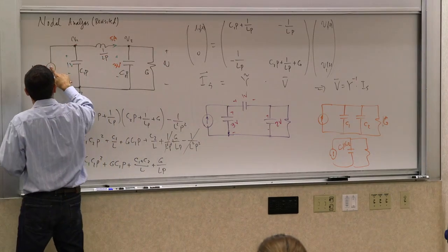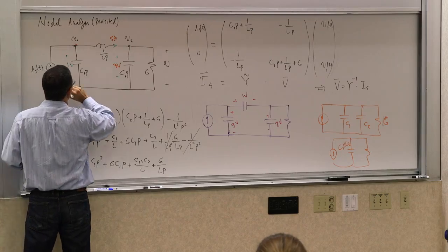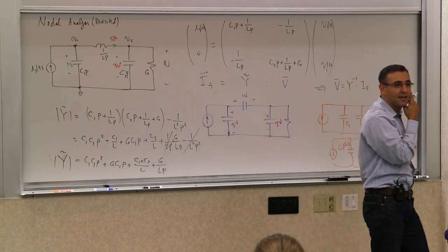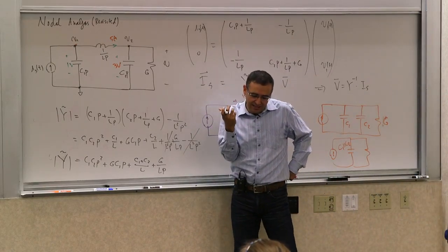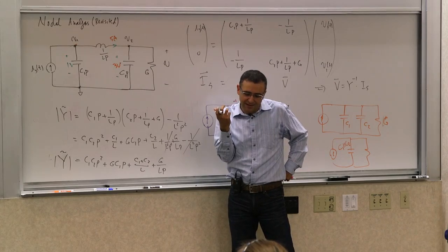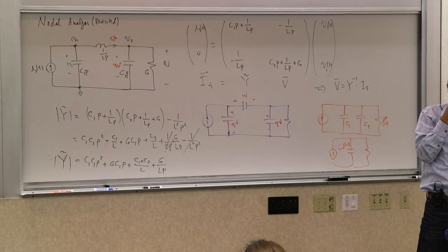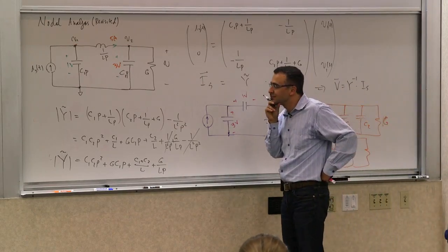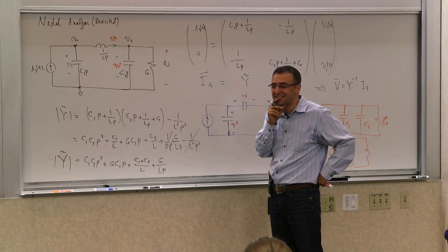So this is interesting because when I have this as a current source, the order of the system should be 3. But if I have it as a voltage source, the order of the system would be 2. That's why it's important, because a current source essentially is, you can think about it as an open circuit that has something added to it. A voltage source is a short circuit that has something added to it. Go ahead. So the answer is 3? Which one? For the first question? The very first one. Okay. Yes, the answer is 3.